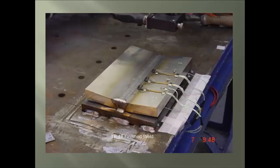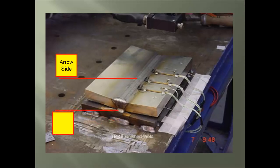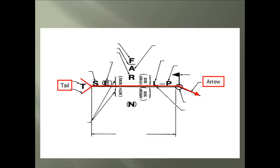Let's look at an actual groove weld assembly, and here is the arrow side, the top of the weld, and the other side would be here. Back at the weld symbol, we cover the actual body line, the arrow and tail, plus we see that there is the arrow side, which is on the bottom of the line, and the other side, which is found above the line. Now, we will cover notations of importance.